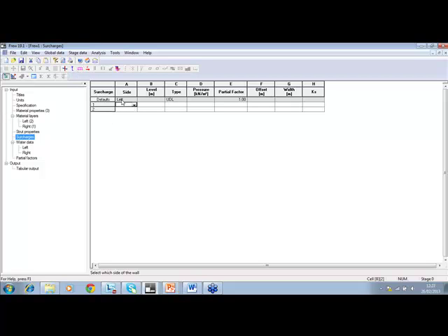So when you go into the table input in Frew, you'll notice that there are these grey boxes at the top. Now these boxes are the defaults. So if I tab on a default, so say for example I'm on side here, I'm in this box in row 1. If I press tab, the default is taken automatically. So this just makes things much quicker. So for example, if I know every time my side is going to be left, I can just tab through it instead of typing left or going and clicking on left, for example.